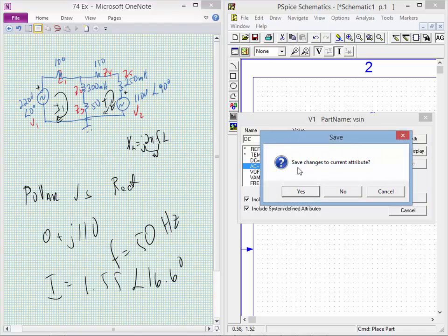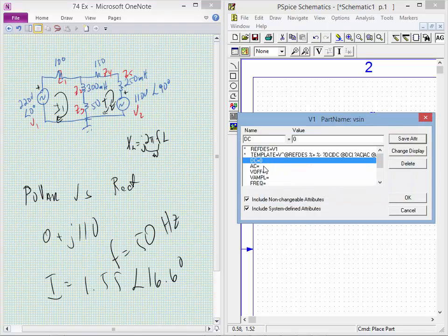We're going to set the AC value to 0, and the reason is because when you specify an AC source in PSpice, it uses AC values if you want to do, for example, a frequency sweep. Probably next week we're going to be looking at doing a filter analysis using PSpice or MATLAB, where we're going to spend a little more time with the logarithmic plots.